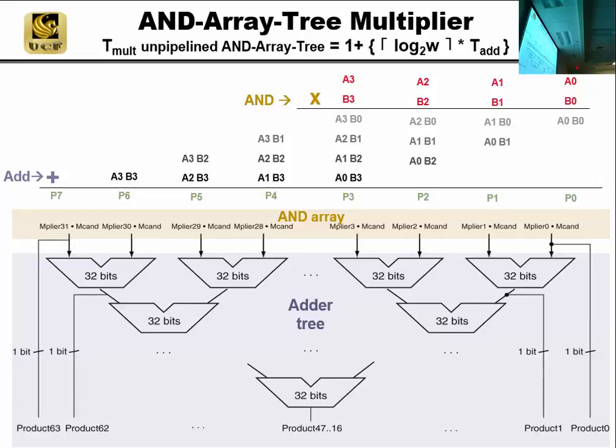Those are the cases. So we're saying here, 0 times 0 is 0, 0 times 1 is 0, 1 times 0 is 0. This is A times B, which we're writing over here as just AB, shorthand. 1 times 1 is 1. Is that any Boolean function we know? It is AND. This is so cool. To multiply 2 bits, what gate is it? An AND gate. An AND gate generates A times B. Really? Yeah. You multiply a single bit times a single bit, and all you need to do that is an AND gate.